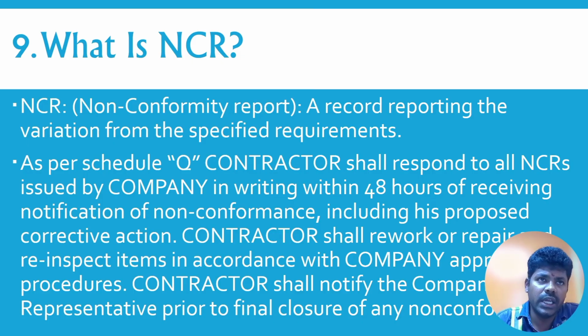If you see any variation from the code, you raise the NCR, but the NCR must be closed within 48 hours. We need to complete those issues and close them. Sorry, it's not as soon as possible, it is 48 hours as per the company standard. We need to follow the company standard and specifications.